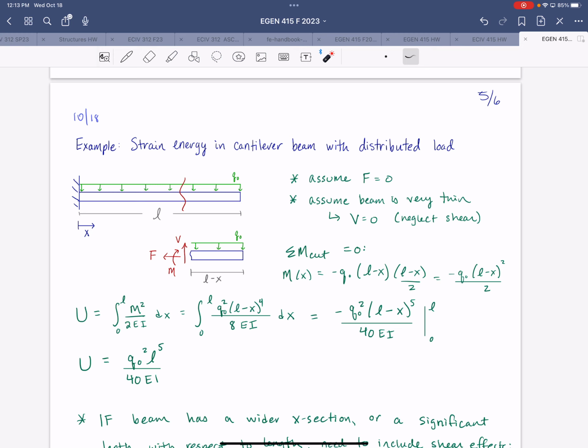There's a lot of shear lag in those moment frames as they flex and shear throughout the length of the building when it's moving back and forth. So that building, because there's a lot of shear deformations, you wouldn't want to neglect the shear contribution. So that's just thinking about it on a bigger scale.